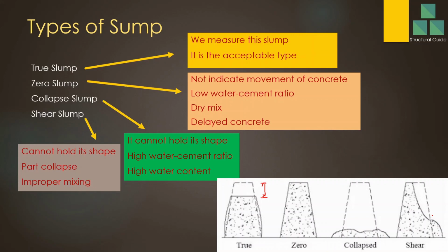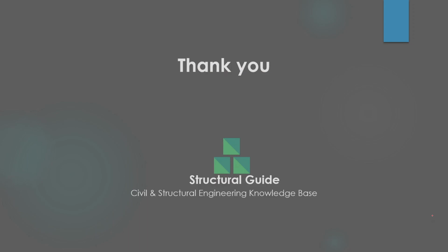Therefore, we have to be careful with the slump test. We have to do it regularly. For each and every truck we have to check the slump, and we have to make sure it is within the limit. With that, we are going to end today's discussion.